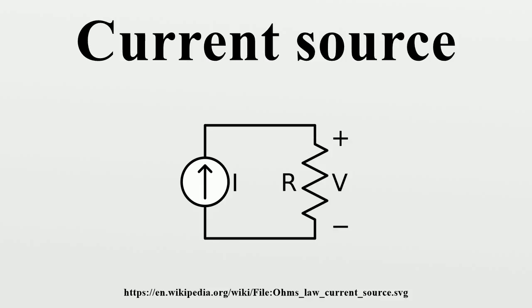The voltage follower adjusts its output current IOUT flowing through the load so as to make the voltage drop VR equals IOUT times R across the current sensing resistor R equal to the constant input voltage VIN. Thus the voltage stabilizer keeps up a constant voltage drop across a constant resistor, so a constant current IOUT equals VR over R equals VIN over R flows through the resistor and respectively through the load.